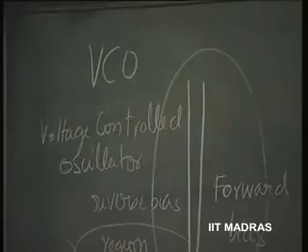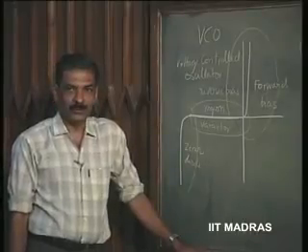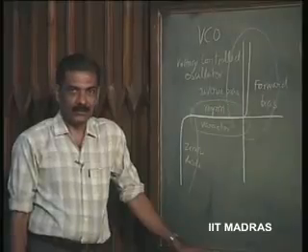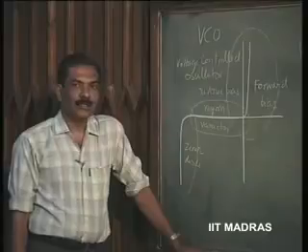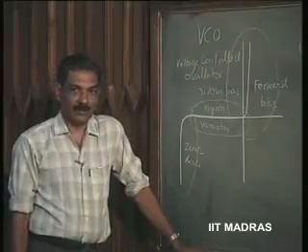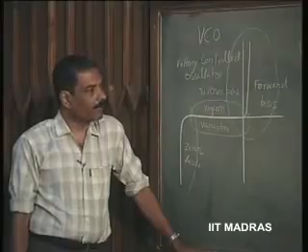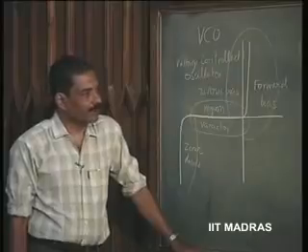can use this variable capacitor, or a filter which has to be tuned, voltage controlled filter, voltage controlled oscillator, all these things use this Varactor diode for varying the capacitance of the network, thereby vary the frequency of oscillation or the frequency of the filter.